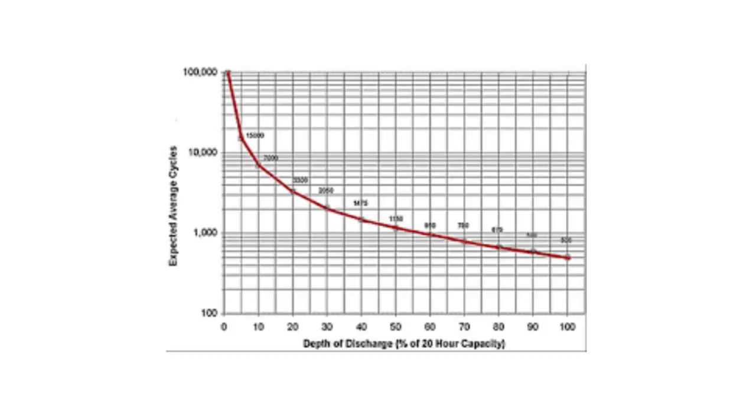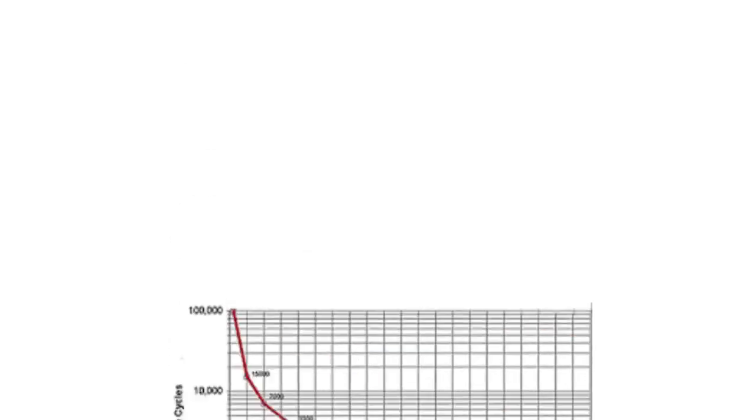Battery bank therefore should be designed above the capacity for which the battery backup is required. For instance, if for a fixed power output 2 hours of battery backup is needed, then the battery bank should ideally have 3-hour capacity for the same power.